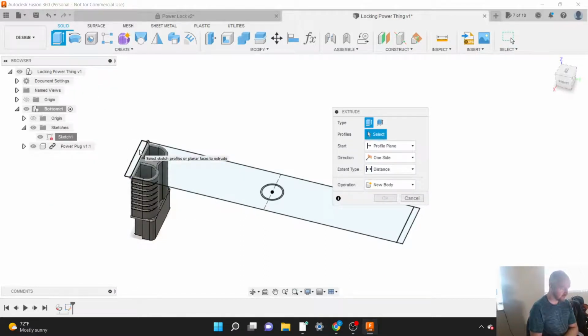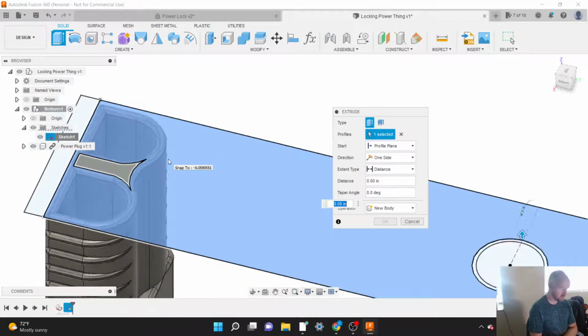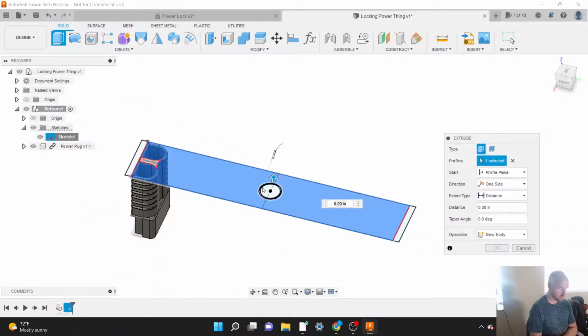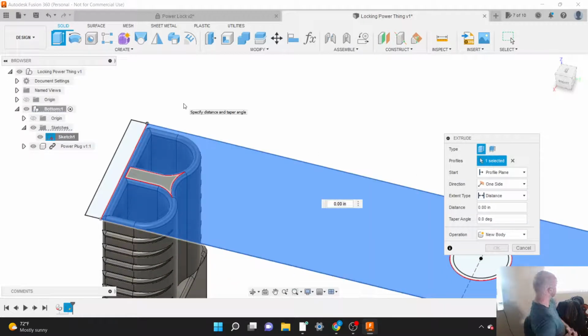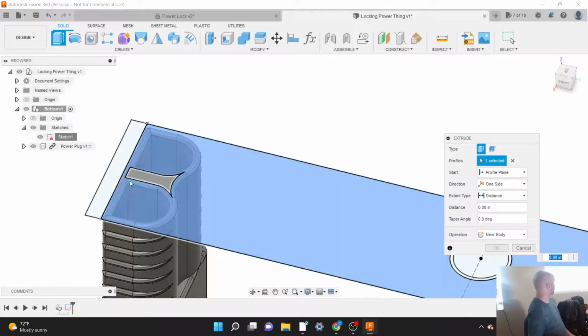And the first item that I'm going to extrude, I think, is going to be this plate on the very bottom here. So this center large rectangle bit here. Because I chose to make my sketch on an existing surface, I have an extra little bit to click on here. So this was the flat part that I created my sketch on.